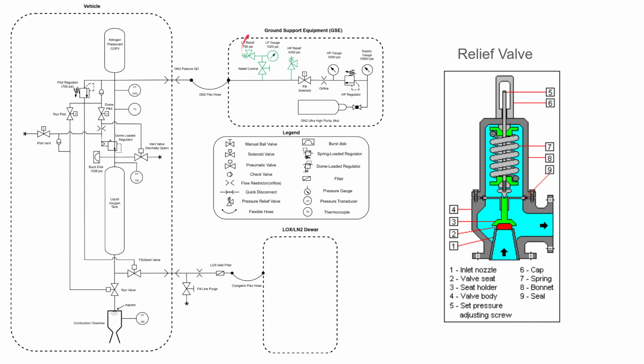This mechanism is our low pressure relief system. So in order to close our fill valve, we need to pressurize the system to about 700 psi while there are a couple members present near the pad. And in order to make sure, again, there's no human error, nothing goes wrong while people are near the pad, we open this ball valve, which is the same kind of valve that's down here. We open the ball valve and allow the COPV to be connected to a gauge and a low pressure relief valve. So this is to make sure that the pressure cannot exceed 750 while there are members nearby.